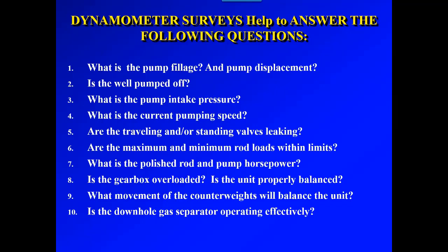Measuring the minimum and peak polish rod loads, measuring the minimum and peak rod loads. Determining if the gearbox is overloaded, and can I balance my pumping unit? We utilize the power clamps, but we can also utilize information input into the TWM software in order to balance the pumping unit: crank information, weight information, distance from crank, gearbox information. And finally, is a gas separator necessary in this particular well? One of the things we'll talk about is gas interference, and introduce a little bit about gas lock. Some of the answers you can get to these questions can ultimately help you increase the efficiency and optimize your well.